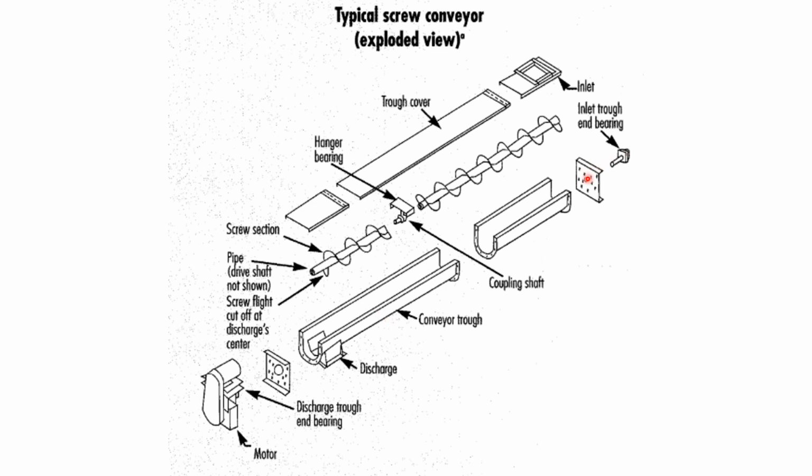Here we have the inlet. At the inlet end we will have a bearing, and at the outlet end we'll have a motor. As per good engineering practice, we always use the drive at the discharge end to have good motor efficiency. This is the screw conveyor here in the middle.